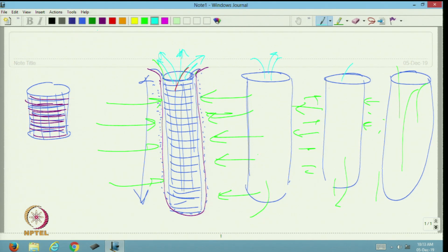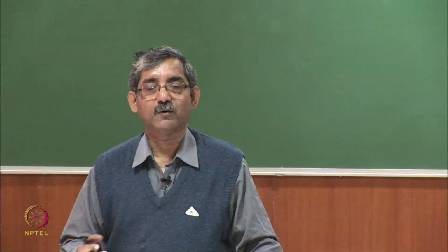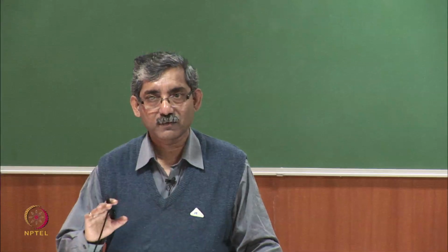Now, with time what happens, this surface is loaded with the filter, and gradually the pressure drop is becoming high. So, this dust cake needs to be removed, cleaned. Here we cannot remove these bags frequently, because it takes time and it is a loss of productivity.